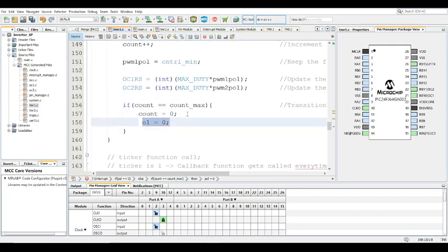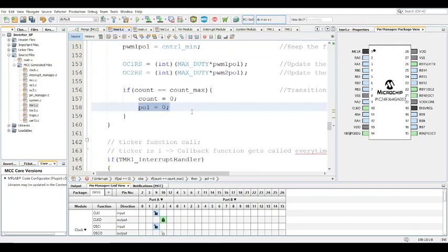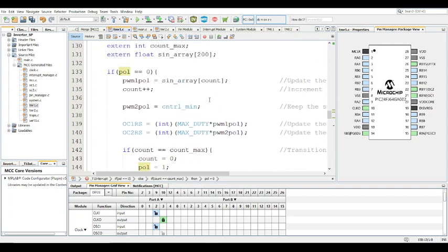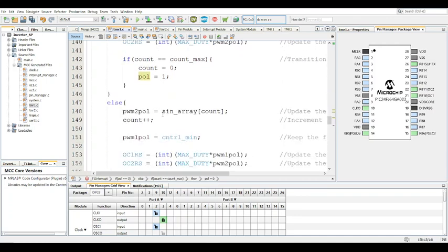Yeah, that's it. That's all there is to an inverter. The SPWM aspect. More advanced inverters, like real world commercial ones, have closed loop control, and for that you have to include a PI control loop here, and AC voltage and current sensors to improve the power factor of the sinusoid on the output. I am not touching on any of that. This is just how to do SPWM, because it's the main thing for an inverter. If you do not have SPWM, then you basically just have a square wave inverter, which is a harmonics-laden inverter. Closed loop systems are quite advanced.